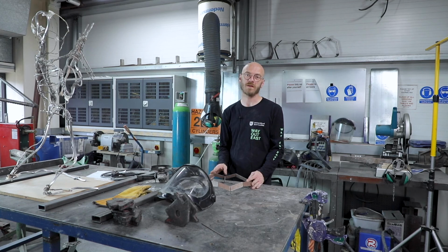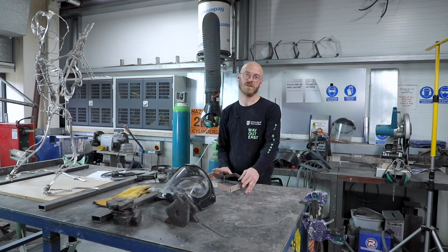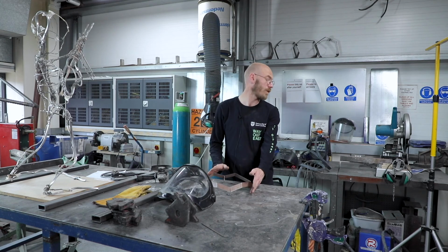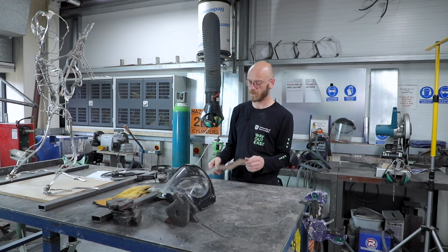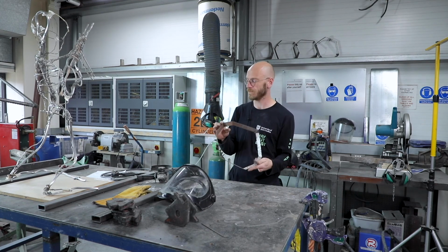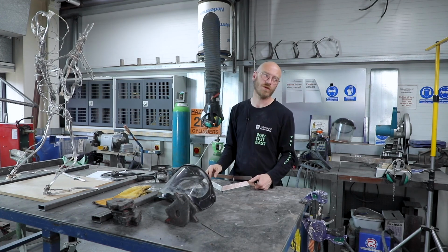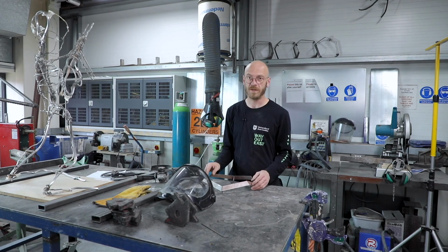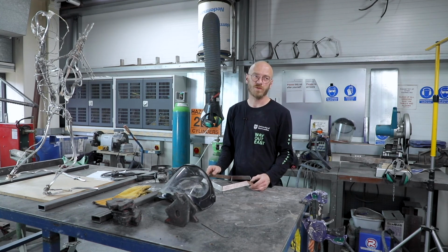Hi, so now we're in the metal area of the workshop, where essentially we cut, bend, shape and attach metal together. Attachment is done with different varieties of welding, so we have the TIG welder, MIG welder and then the spot welder. Spot welder is a very quick way that you can create forms with thin steel. The MIG welder is a bit more industrial, and then the TIG welder is somewhere in between.